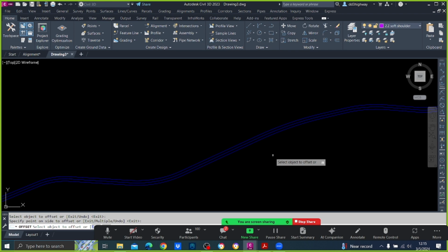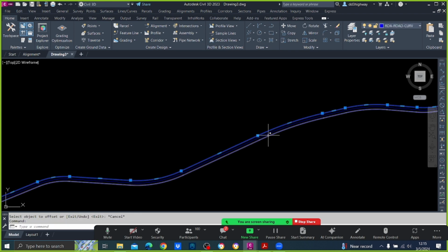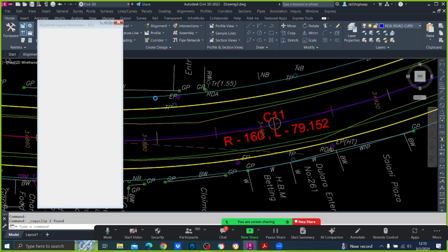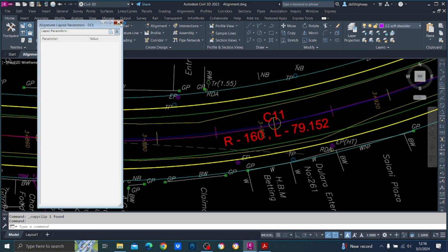Now can you do it? Okay. Now you take these two lines that you offset, edit, copy, and then go to the alignment and paste to original coordinates. Even for this 5-meter line, that's the way. Right. So this is one method of creating the road.